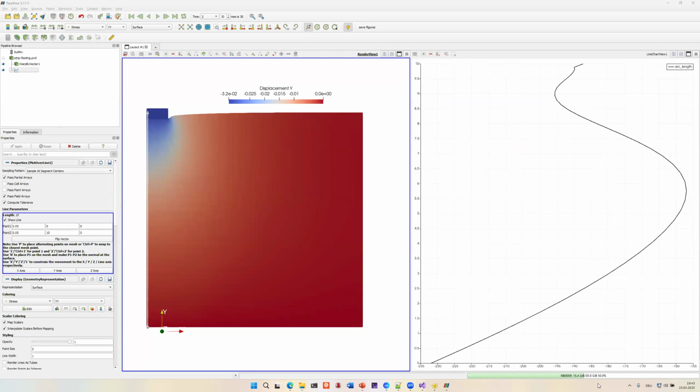Obviously, if you refine the mesh very much and go to the surface, then your integration points go into a very, very low stress state. And most of our soil models behave very badly in these types of stress states. Then you would also have problems in NUMGEO. But again, it's a matter of whether we are in an admissible stress state or not. Other than that, we have not encountered issues with mesh refinement, at least in the convergence studies that we have performed so far.